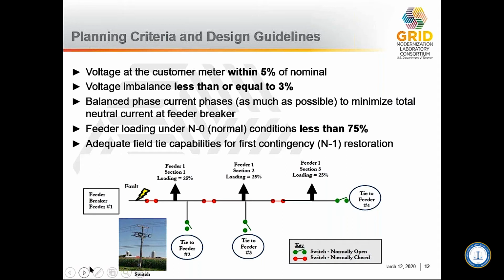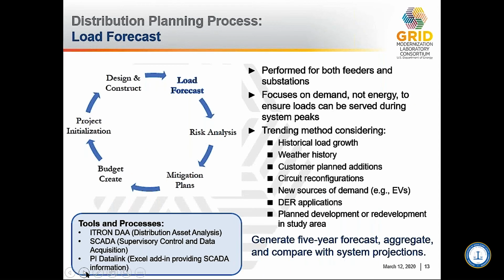When the total feeder circuit utilization in a study area exceeds 75%, then this transference of load is no longer effective, and more elaborate solutions now need to be employed. Next slide. So that takes us into some of the more extensive distribution planning mitigation measures.